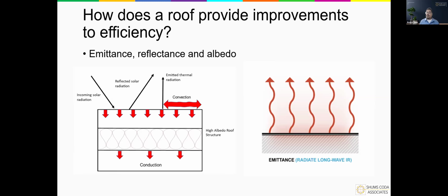And then albedo, especially, is one of those discussion points about color. And that's really, I mean, we're getting down to architectural design or preference and consumer preference. But it's no surprise that a black roof, like a black TPO or EPDM roof, for instance, is going to absorb a lot more heat than a white PVC or TPO roof, right? That albedo is going to be able to direct that away from the building and prevent it from being absorbed into the rest of the assembly.